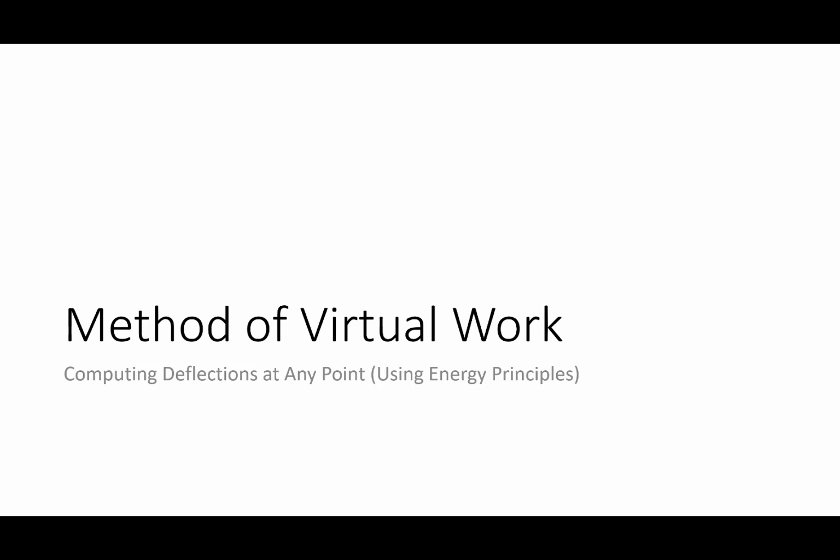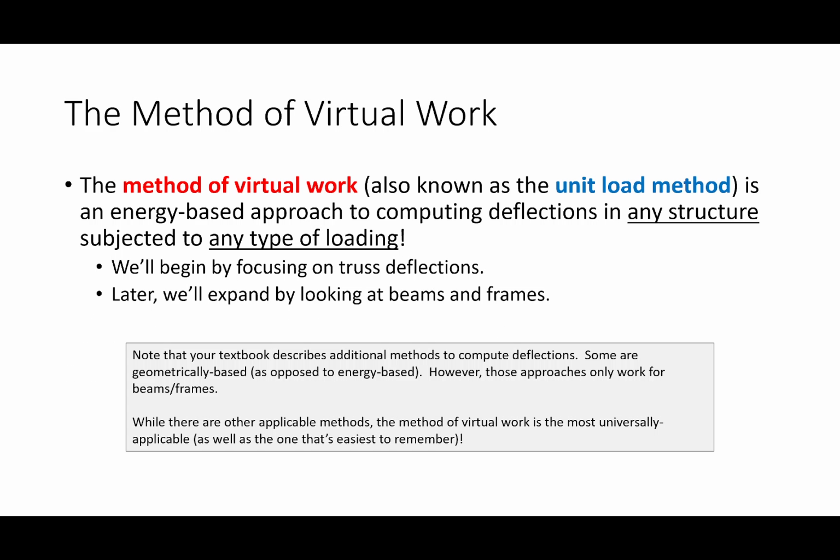Just so you are aware, if you open up your textbook, it will be broken up into 2 broad classes of how to compute deflections. You're going to see listed energy methods, and you're going to see listed geometric methods. Okay? Geometric methods are very specific applications for very specific types of problems, mainly beams and frames. But energy methods will work for any problem, any load, anywhere. Okay? So that's why I focus on energy principles, because it works across the board for any problem. And it's really easy to follow. Okay? So the method of virtual work, sometimes it's called the unit load method. It's an energy-based approach to compute deflections.